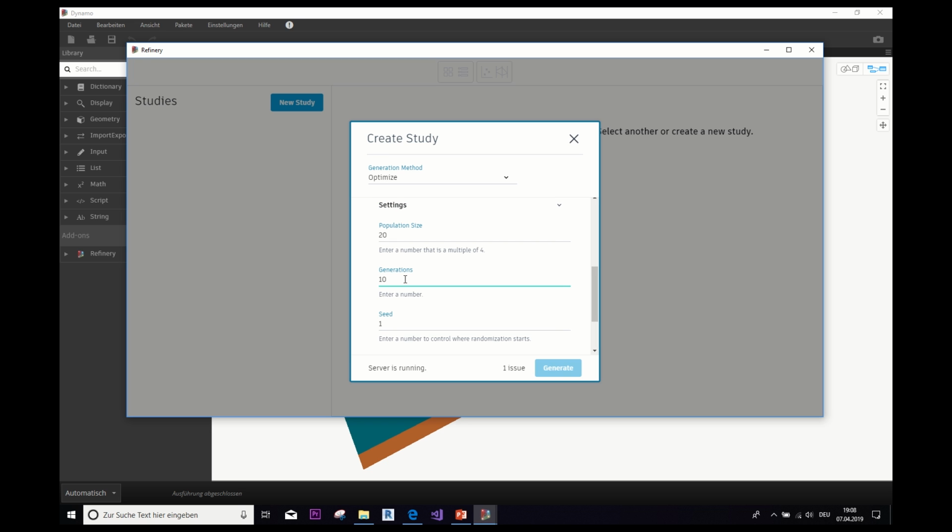And what these three values mean is, seed is how many designs you start with. So how many random designs it will start with in the beginning and then develop further. This is basically the first generation of designs. This can be one, but maybe you would want a more diverse base for your study. So let's input maybe 5.